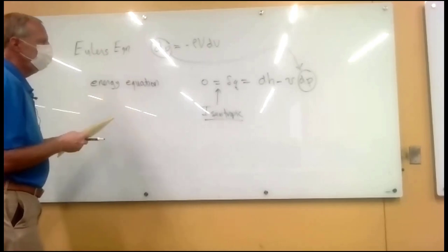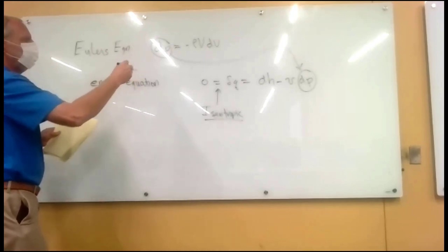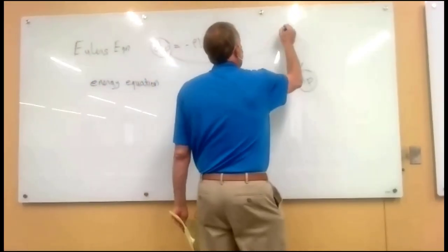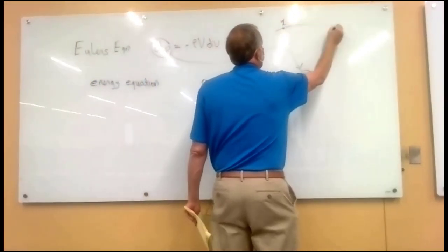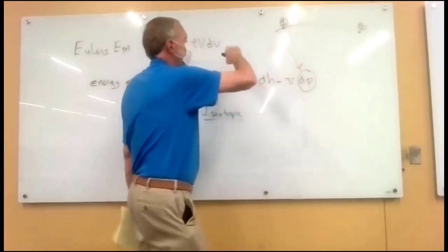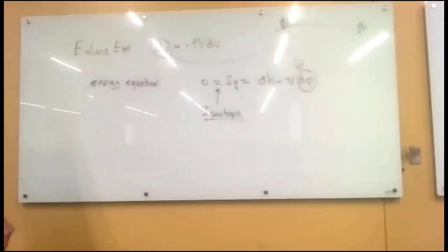So what we need to do is essentially some algebra on this and then integrate between 2 points on a streamline. So it's the same old philosophy. We're going to be here, and then we're going to add up all of the pressure differences and velocity differences from here to there. And integration does that incremental adding for us.